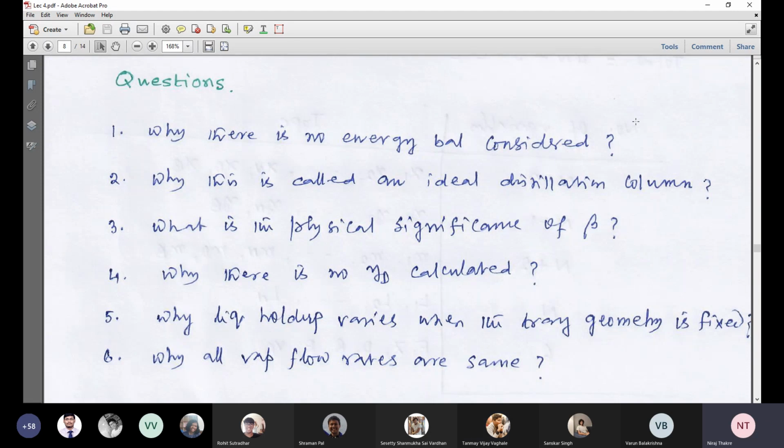That is basically a heat exchanger model. Yeah, that also we can consider, no problem. But these energy balance equations are mainly specific to the tower. Okay, sir. I was thinking that it also includes both reboiler and condenser. No, it's not really. That one assumption is there. You see, thermal dynamics we are neglecting. But definitely, if we want to make the model more rigorous, more accurate, we can also consider that. And that is nothing but a heat exchanger.